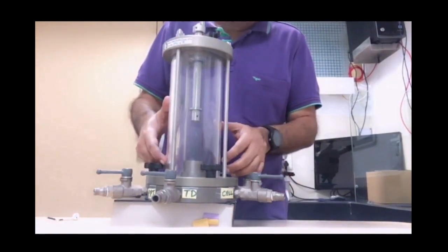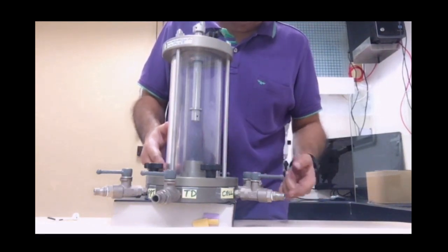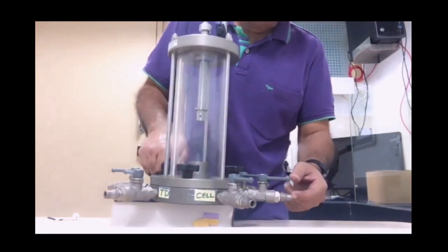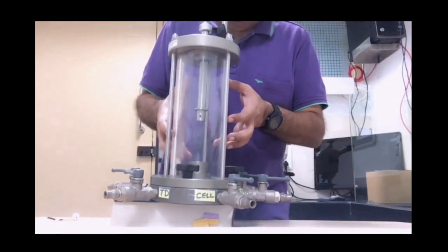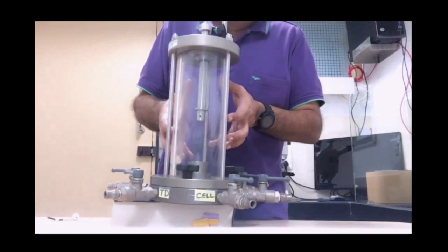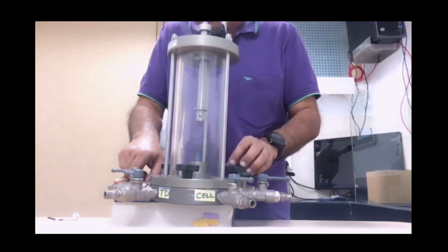But during this process, you may find the water is still going in, because the water goes on inside from this back pressure line. If water is still going in, you can expect that some amount of air voids are still being filled with water. So not necessarily the gauge gives you the correct reading in those cases.